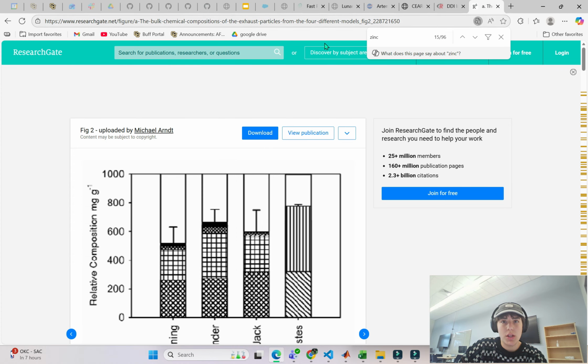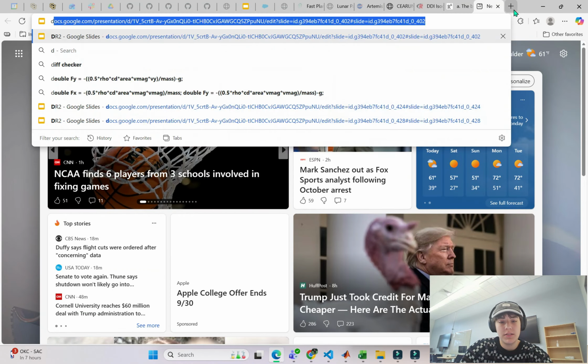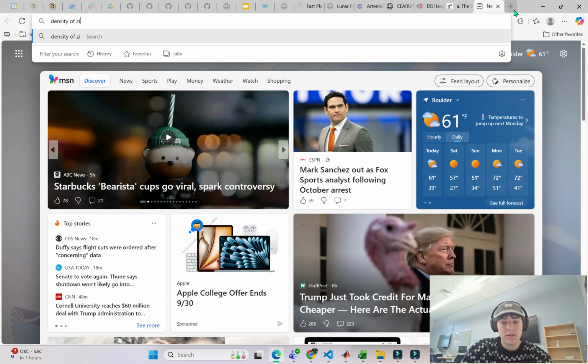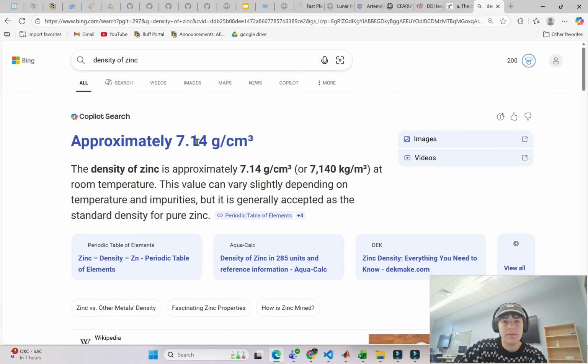You just look up the density of zinc online, use this value. Make sure all your units are consistent. You multiply by the percentage that you choose that makes sure that the solids are within 82%. So the solids are zinc, ammonium perchlorate, and aluminum powder. The percentages of all those components should add up to 82%.